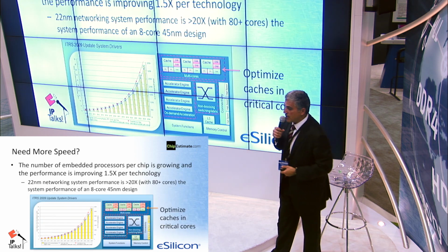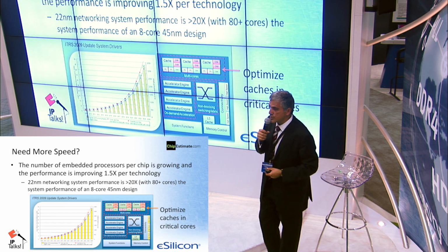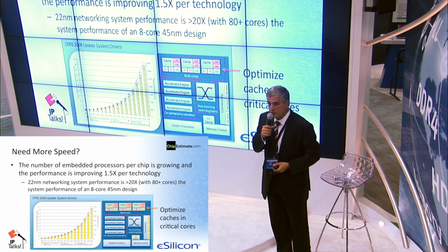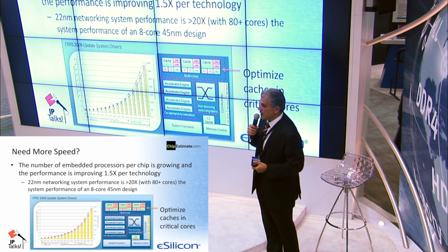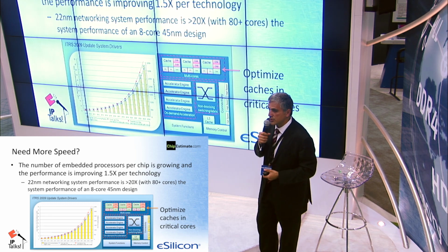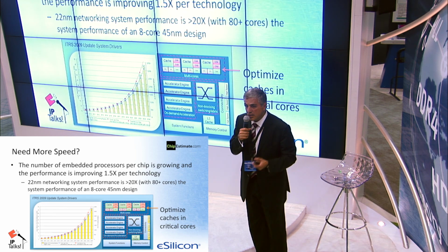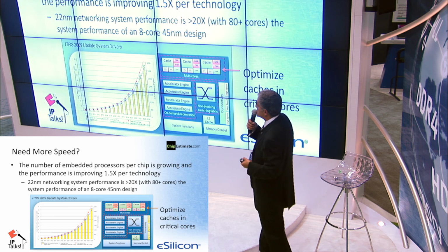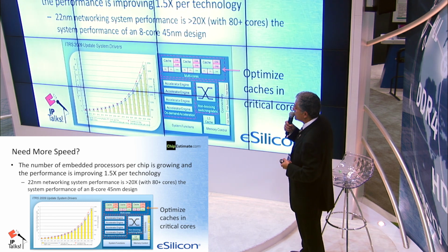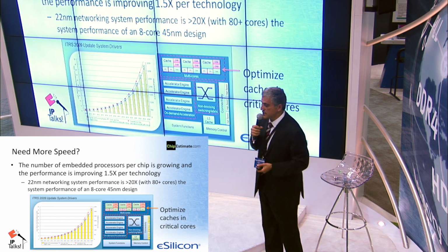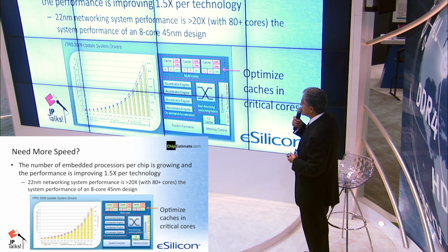Another example might be where an application requires more speed. The same sort of phenomenon applies there. You look at the number of instances being used, and what's on a critical path. If you take memories coming out of compilers and use them as is, you have a lot of overhead and burden associated with that, because they're designed in a compiler kind of methodology. You strip those down of the overhead for that specific critical path, and you can then design something a lot more efficient and productive, especially in the case of building fast cache instances for high-speed processing and subsystems in a lot of the multimedia and mobile applications.